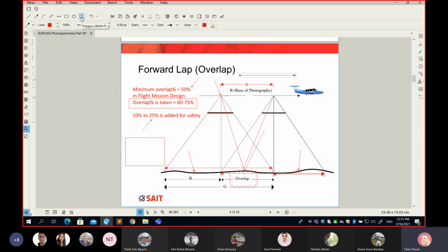So I go here and I say, let's fly this way. After you finish your first flight line, you go this way and then go back, and then you go back. So kind of a zigzag thing. So you go on parallel flight lines or parallel sweeps of the ground until you scan your entire area. If you remember, this was shown in several videos.